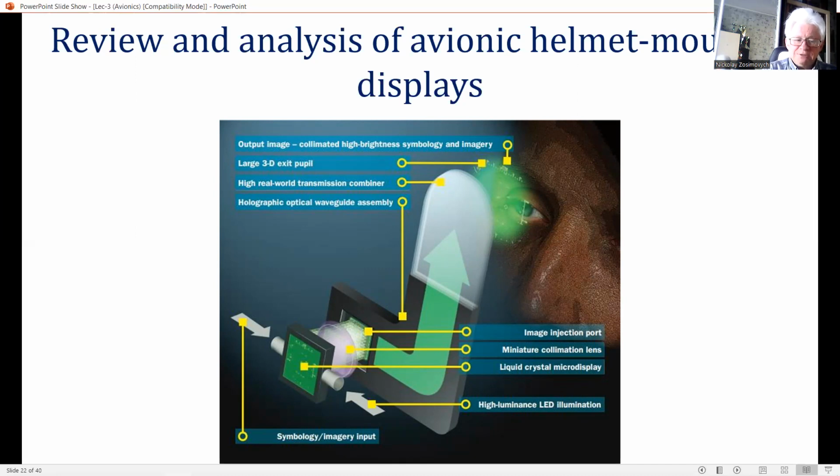Image intensifiers are highly sensitive detectors, which operate in the red end of the visible spectrum, amplifying light about 40,000 times from less than starlight up to a visible level. It should be noted that special cockpit lighting is necessary, as conventional cockpit lighting will saturate the image intensifier. Special green lighting and complementary filtering are required.